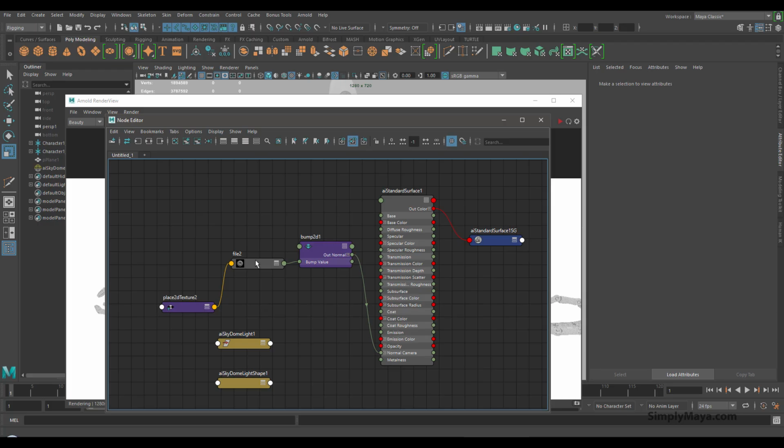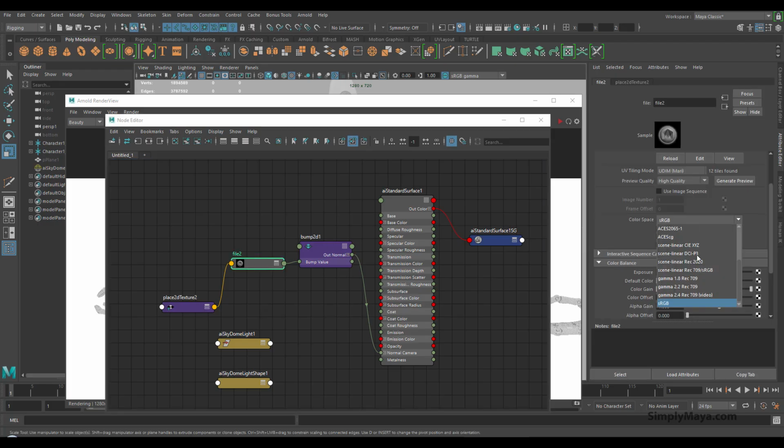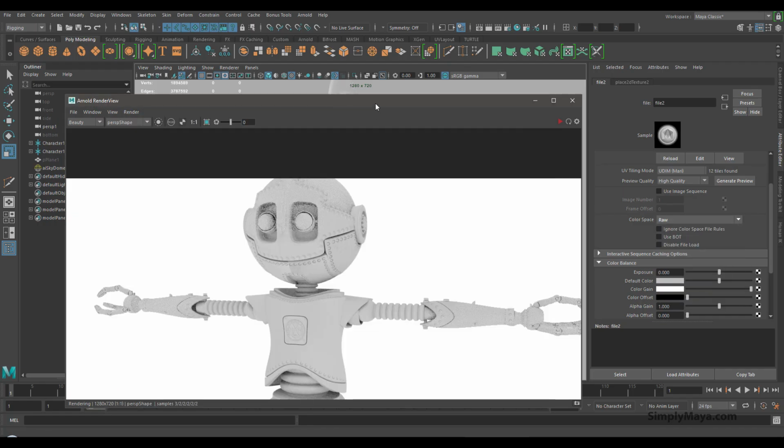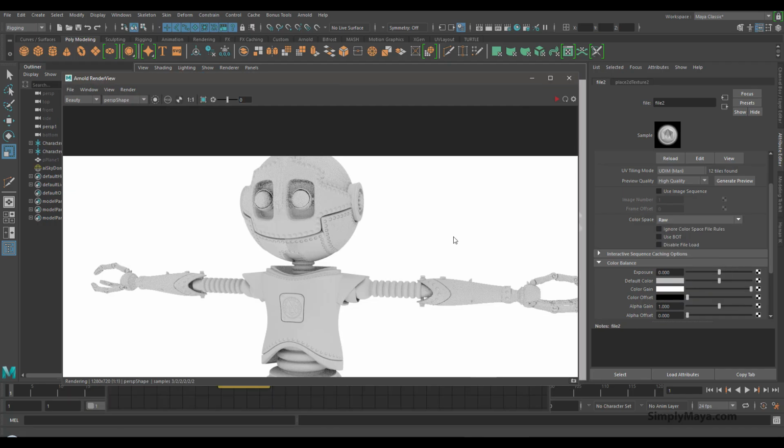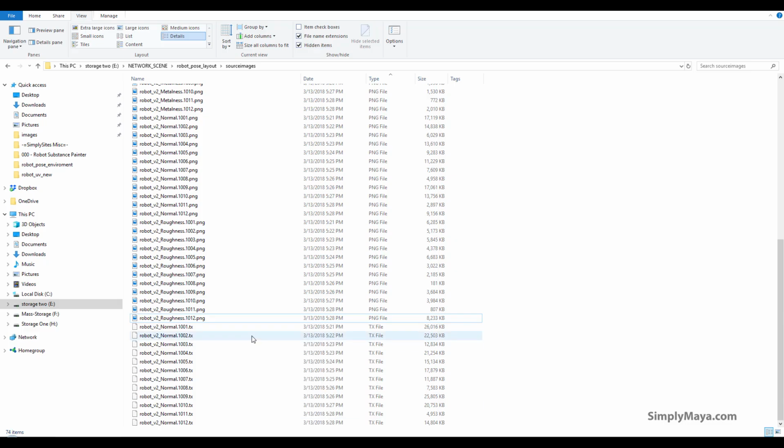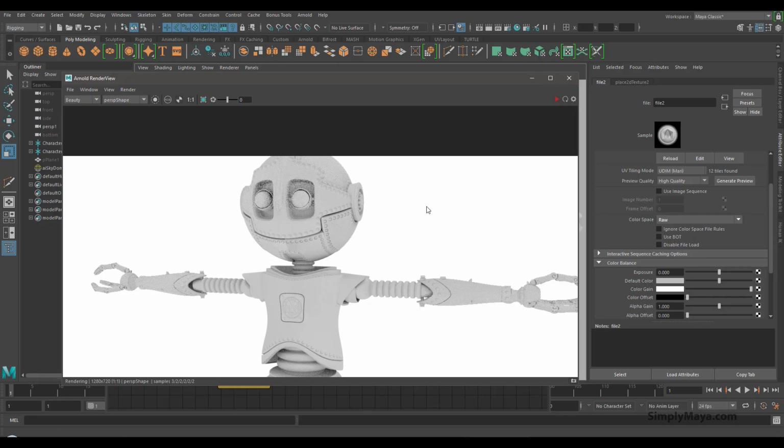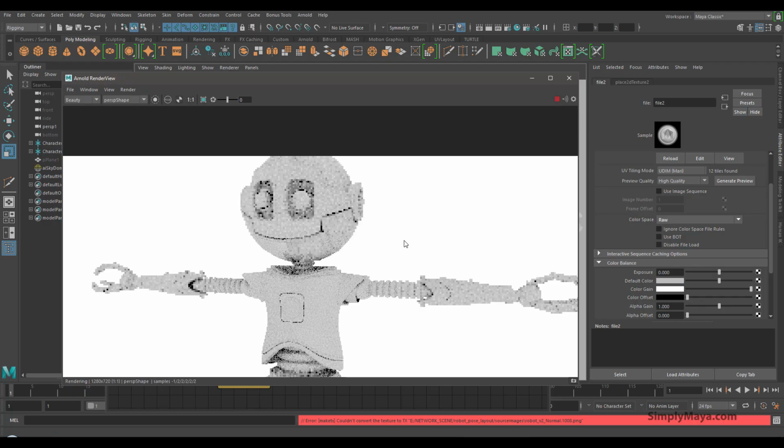So why did I come in and do it wrong on purpose? Because I'm now going to flick this to raw, and I'm going to render again. And a lot of the time, because Arnold has already created those TX textures and it's marked them in use, when you hit render, sometimes it works and sometimes you'll just get a big error. Arnold down here will say, I cannot convert these textures to the new TX values, and I want to show you how to deal with that if it happens to you. Right, there we go, it happened.